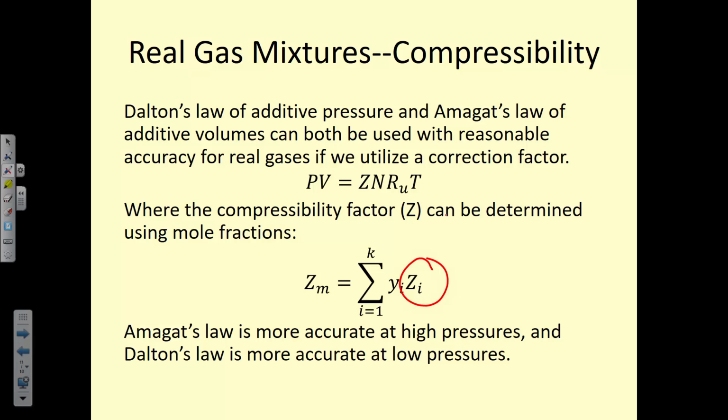Okay, that's why I was trying to figure out if one way is better than the other, but you compare the answers, assuming that it's an ideal gas. Right. And then the actual. Right, and then you see how much percent different it is, because in some cases it may be almost the same value. If you're far away from the critical point, then usually it's a good indicator that it'll be better received if you would use it as an ideal gas.